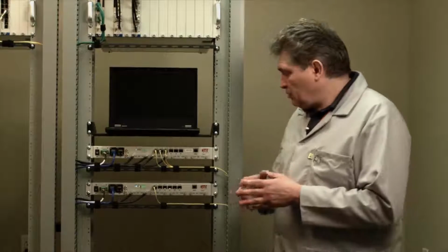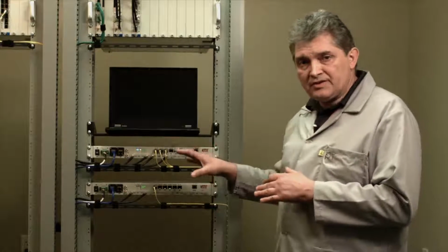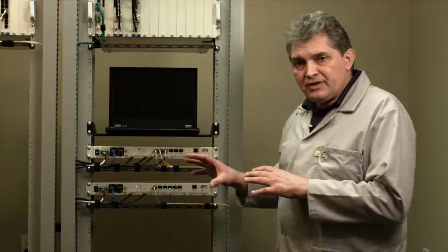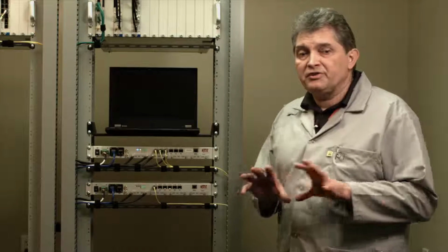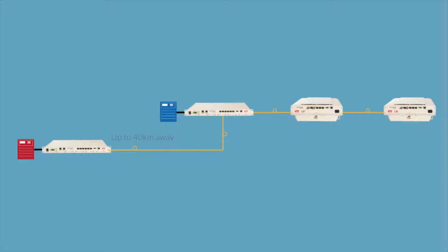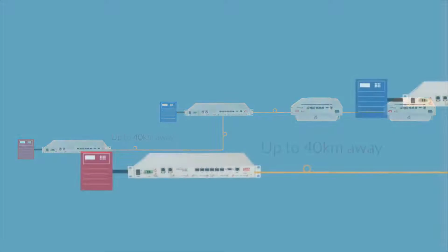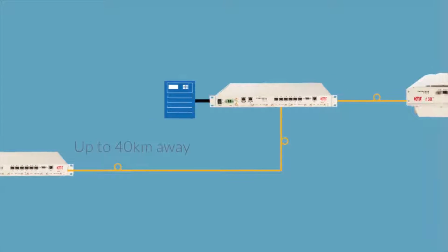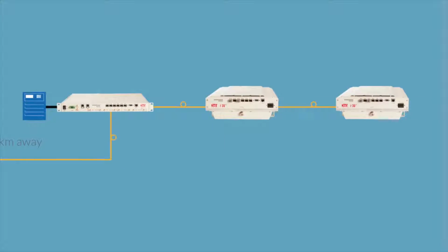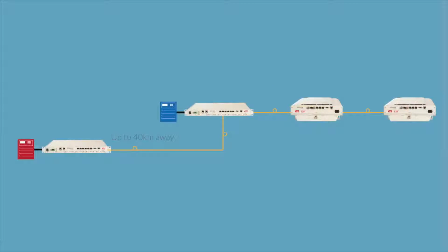Besides the fact that co-located host units can be cascaded, we can also cascade host units which are at different geographical locations. In that way, content, meaning the base station resources which reside at different geographical locations, can be aggregated together and then transported by fiber optic link to our remote locations.